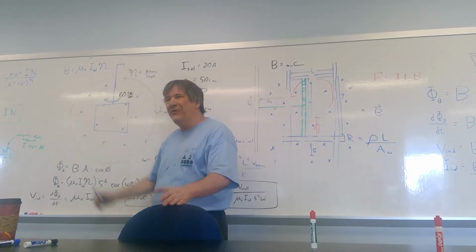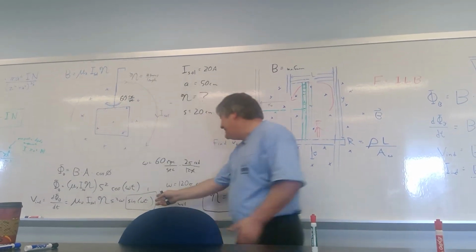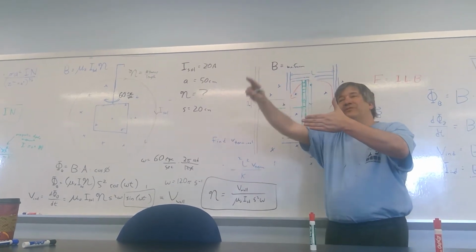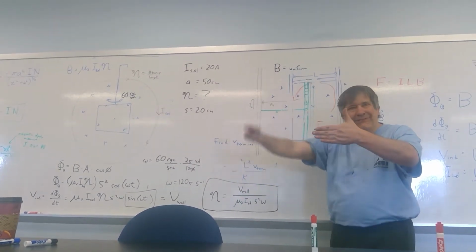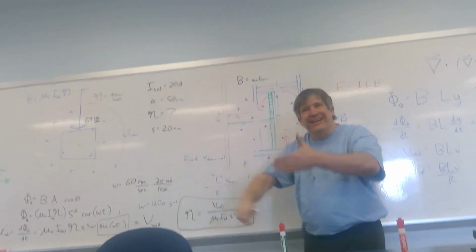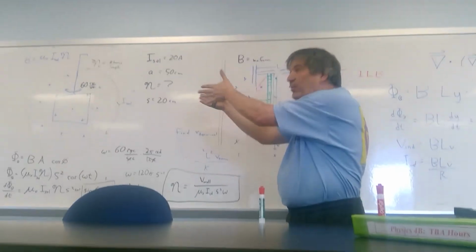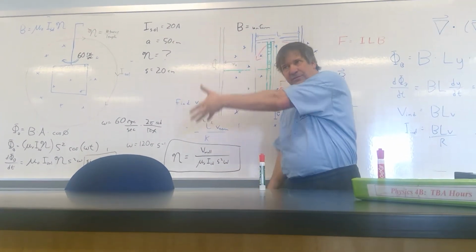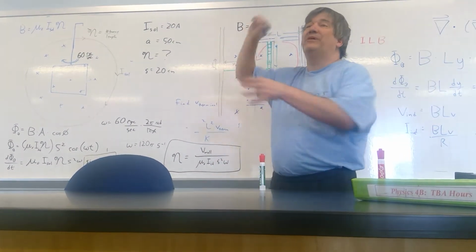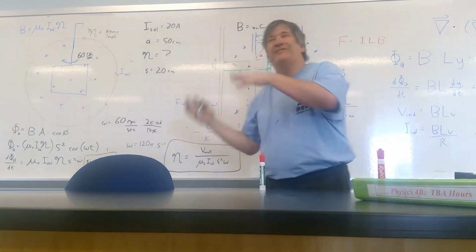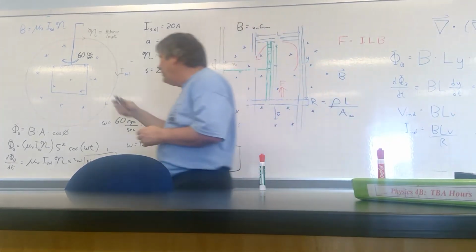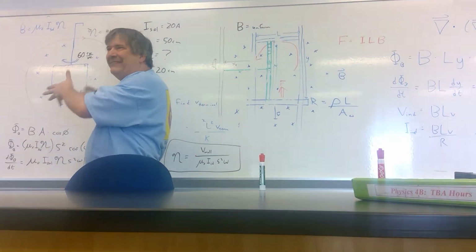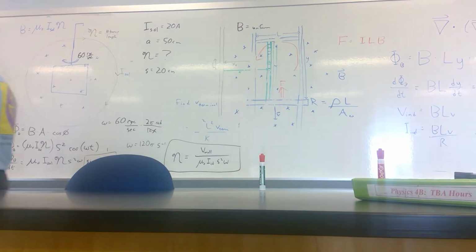And if I had, I would get this induced voltage around every one of those turns. And since all the turns are wired in series with each other, voltages in series do add. So if I did 100 turns of wire on the square loop, I would get 100 times more induced voltage. If I did 5,000 turns of wire in the square loop, now maybe the square loop is getting too heavy to spin with that crank, so that could be a problem in itself. But probably just going with one turn of wire was a missed opportunity to make this a more efficient turbine.